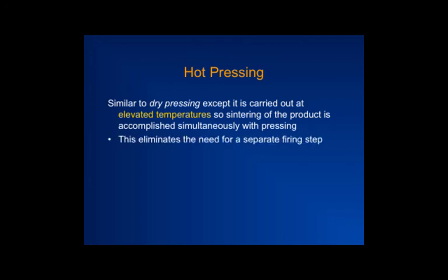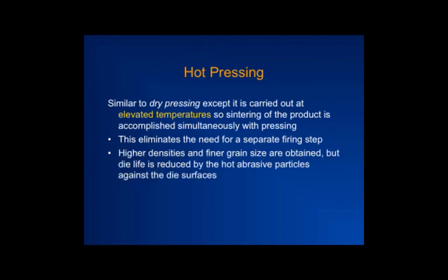Main thing is press it in one direction, you press it in many directions, you heat it, you don't heat it, and you have different ways to create components, and accordingly you can get either low density products or high density products, more uniform density products or not. Okay, when you're trying to heat this material, the typical heating methods are quite slow, and so the heating rate is low, and so your throughput is going to be a lot lower.